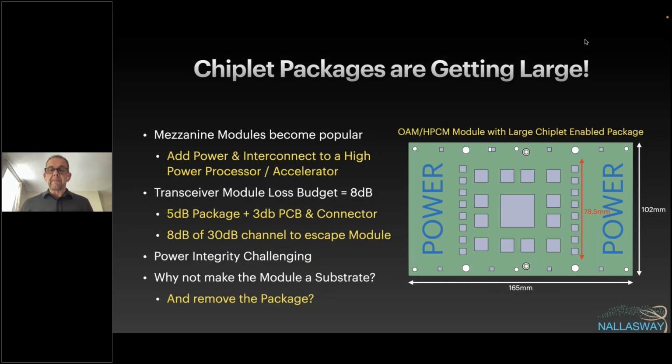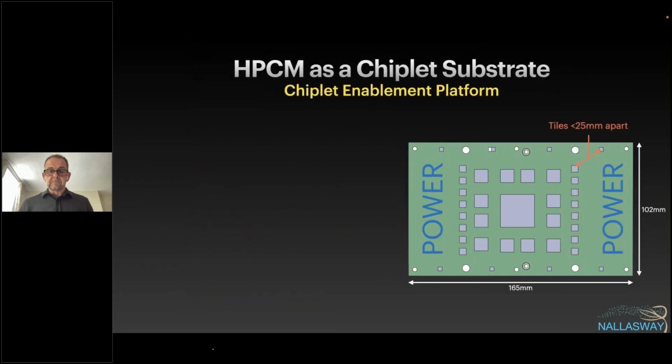So then you're basically saying that that new board would be the same complexity as the package itself now. Like, something like a many-layer ABF type substrate, for example, just even bigger now. Right, you'd bring the HDI of a substrate, where you basically make the OAM PCB into a substrate material with the standard stack up there.